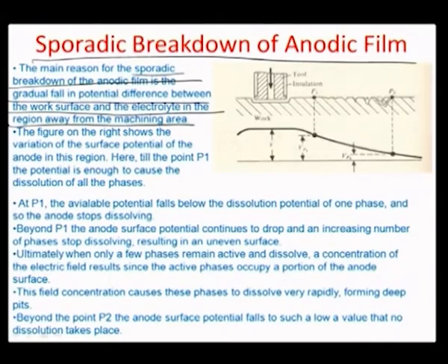Obviously, because let us say this is the electrode here and there is a certain field which is created in this particular gap, which is represented by these lines of force. The fields slightly curl around the corners, and it is also reasonable to assume that this field can extend farther away from the tool surface as well, because the field, as it goes away from the tool, falls off as an inverse square of the distance r. So the field varies as a square of distance from the electrode onwards towards the remaining part of the surface. But there does exist a field.